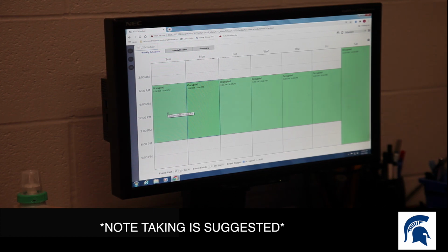You can right click and there's a copy day option. So you could copy whatever other day you have and then put it onto Saturday. You'd want to copy one of the other days. So if you do copy day, and then you can right click there and apply day. Or there should be a paste day. Hit the paste day, it's the second option. Yeah, so now this unit would run from 5 to 6, Sunday through Saturday. That's how that specific unit is configured.